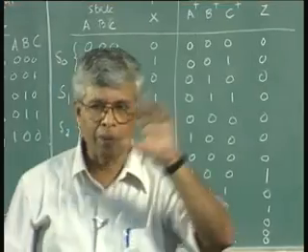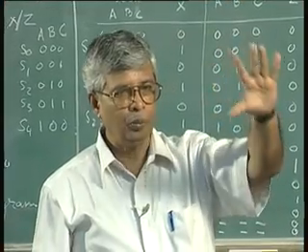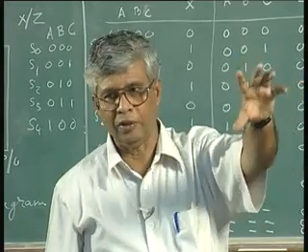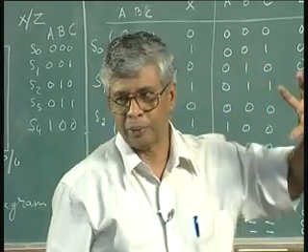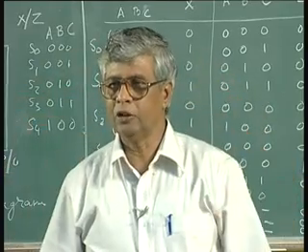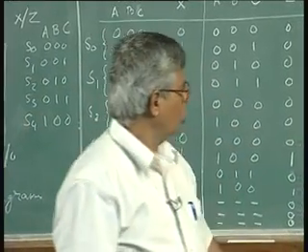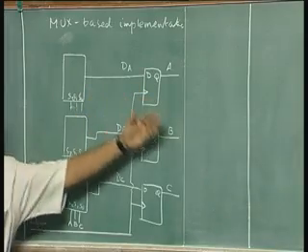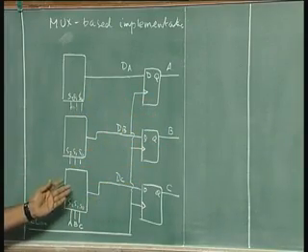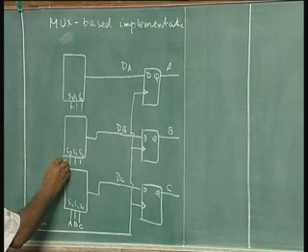You remember that overall block diagram of that sequential circuit implementation. We have this steering logic, the output which is the next state variable is kept in the flip flop, fed back as the present state along with the input, and then you get the next state. Imagine that, visualize that block diagram. So, ABC has to go back into the combination logic, isn't it? That is what this is, this ABC.